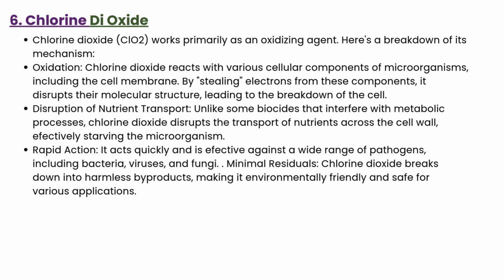Disruption of nutrient transport: unlike some biocides that interfere with metabolic processes, chlorine dioxide disrupts the transport of nutrients across the cell wall, effectively starving the microorganism. Rapid action: it acts quickly and effectively against a wide range of pathogens including bacteria, viruses and fungi. Minimum residual: chlorine dioxide breaks down into harmless byproducts, making it environmentally friendly and safe for various applications.